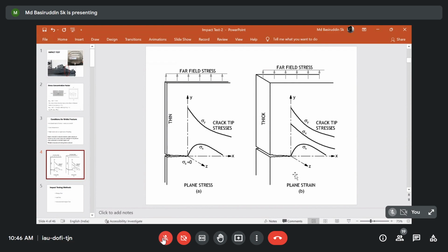But if your testing temperature is a little bit low, or in such a condition that your applied stress is not reaching the yield stress values, but your applied stress reaches the fracture stress value, that is why you will find that your applied load is not reaching up to the yield strength value such that plastic deformations will happen. Material fails before reaching the yield strength values. That is why no plastic deformations will happen, and the materials will fail in a completely brittle fashion.